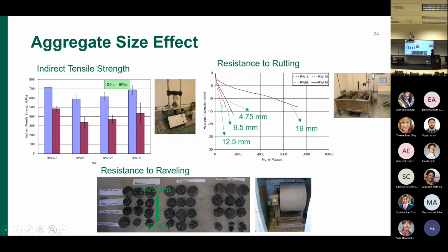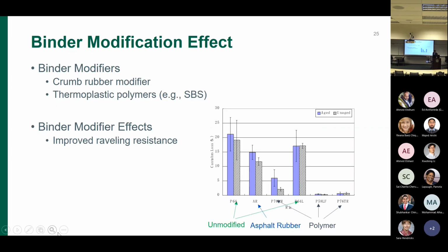Okay. So not much in terms of that, but we think there are some improvements. Okay. So we see the benefits in the use of small aggregate size in the production of the porous asphalt mixture, with some reduction in the permeability and hydrologic properties.